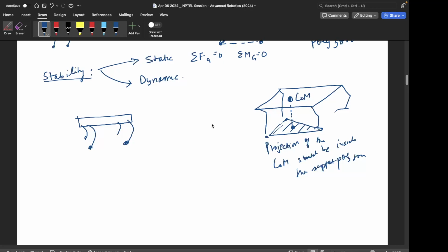If I tell you to just keep your foot on the pedals and just be there without moving ahead, without pedaling, at zero velocity, then it is not possible, right? The bicycle will start falling down to either of the sides. So the bicycle is dynamically stable. You're riding a bicycle, that is a dynamically stable system, right? A statically stable system is like, let's say, a table, right? A table with four legs, that is statically stable.